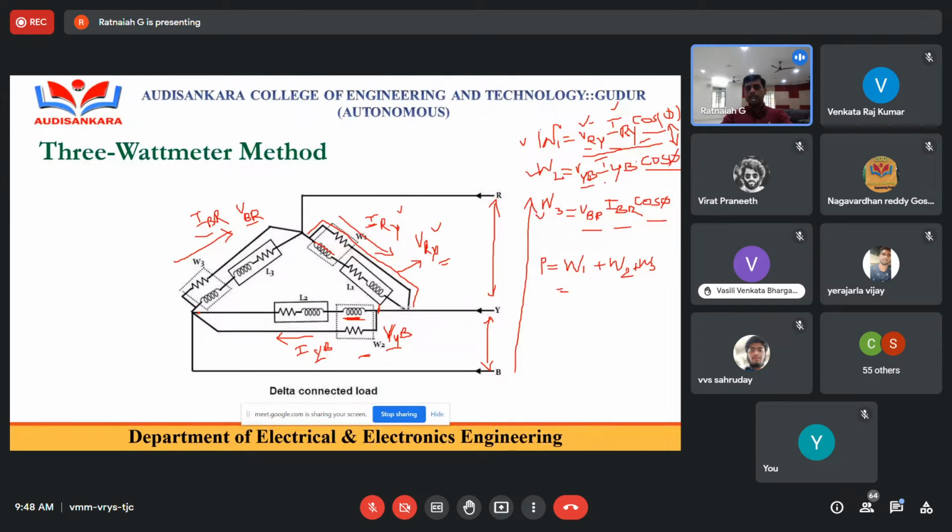Similarly, the next wattmeter reading is also V phase, I phase into cos phi, and the next also. Therefore, there are three wattmeters with the same reading. So I can take three times V phase, I phase into cos phi. So the total power absorbed by the load is three times V phase, I phase into cos phi.